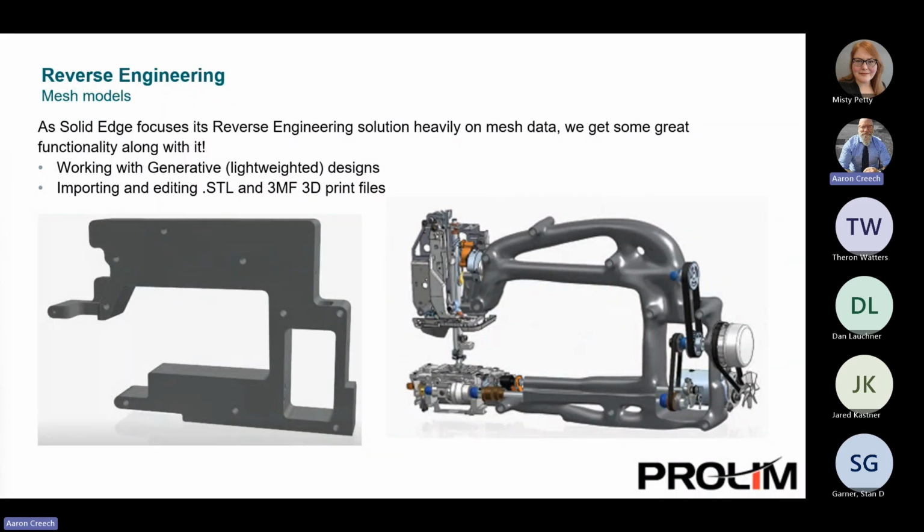Okay. So again, Solid Edge continues to focus efforts on improving technology for this reverse engineering design, and we see it every year or so. So giving us the ability for AI-generated generative design functionality, also referred to as topology optimization. So this functionality allows the software and its algorithms to generate hundreds of designs based on some very basic input or parameters that need to be maintained. And in minutes, not hours or days, several algorithmic design options are available for the user to review and determine which generative design concept works best for their project.